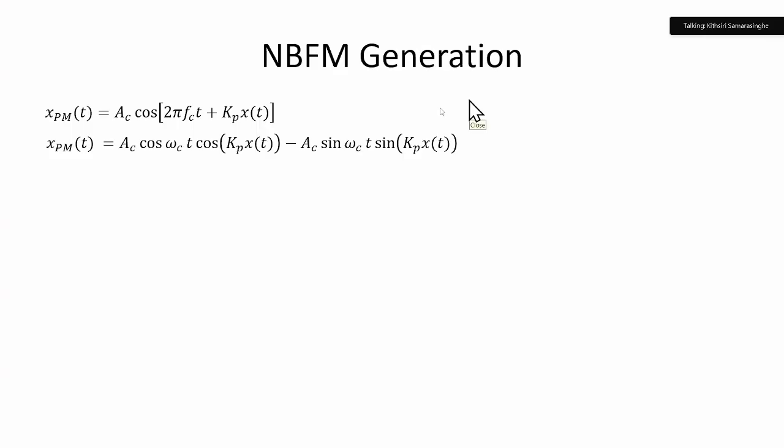One question Bandara is asking: why the stability of signal changes? Can you explain it further? It was not clear. Okay, thanks. Stability means the ability of the oscillator circuit to maintain its output frequency constant. When you use LC circuits or RC circuits as your tuning references, they are not highly stable. Your output frequency of an LC oscillator or RC oscillator has a stability level such as plus or minus 10 parts per million. I'm giving approximate values, right? Around 10 parts per million.